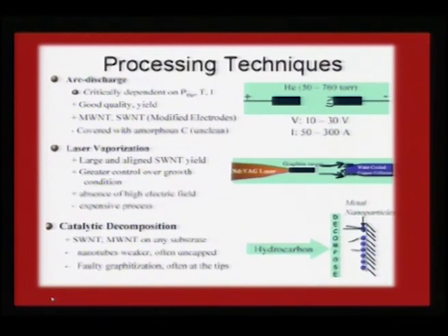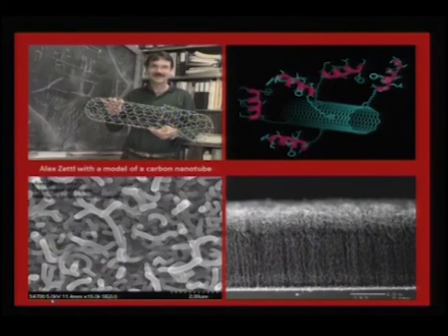These I have included just to give you an idea about what arc discharge is. You have the two graphite rods kept in vacuum in a helium atmosphere, then you get the discharge and trap the carbon soot. Or we can shine a laser on a graphite rod and trap the soot in a water cooled copper collector. Or we can take a silicon dioxide wafer, put some nickel film on it and run a hydrocarbon over it, and when this is heated it decomposes the hydrocarbon to carbon nanotubes on the nickel metal. So, these are various ways of getting single wall or multi wall carbon nanotubes.